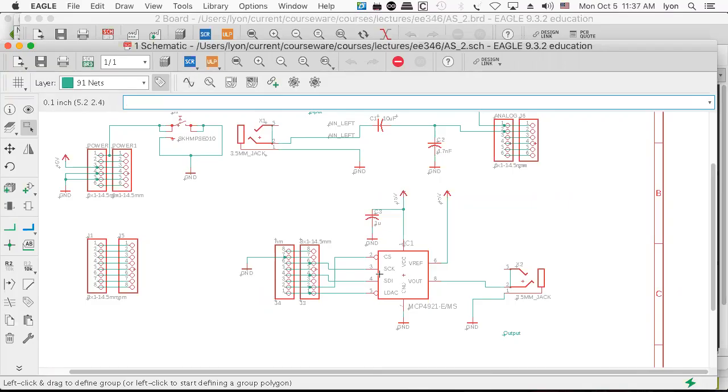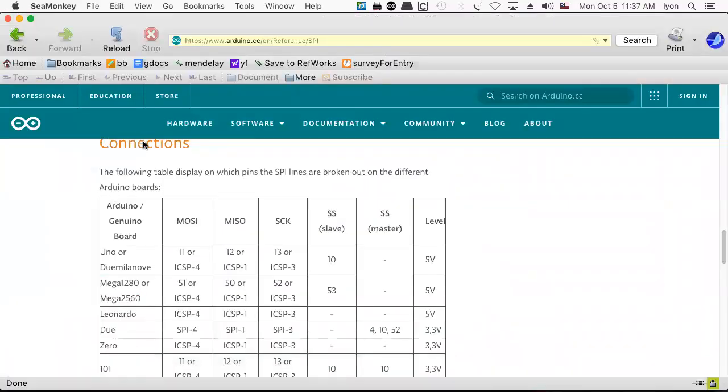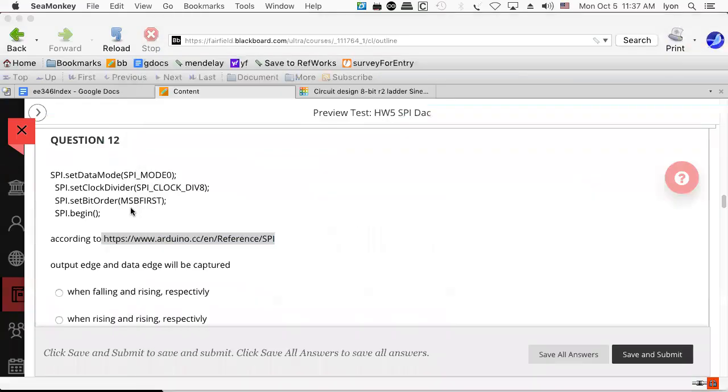And here you can see the serial clock, serial data in, chip select, and there's that LDAC that we were toggling before. And what you would do to learn how to use that is you'd read the data sheet on the MCP4921, which is kind of neat. So it's interesting that you should ask that question because it gets you kind of deep into SPI and how the actual DAC is working.